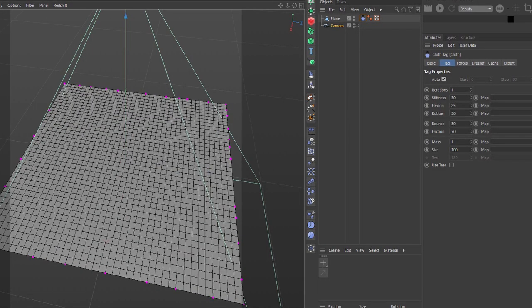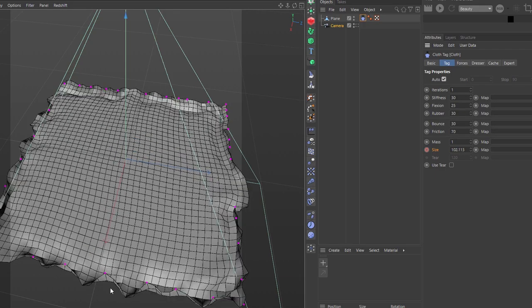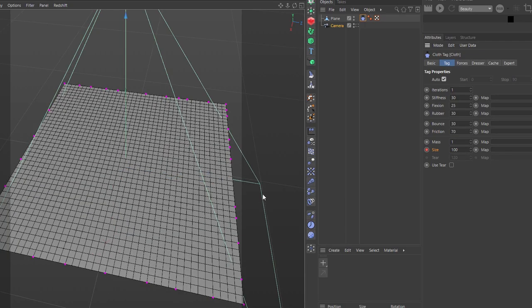And one more trick, we're going to size and hit this middle button to add a keyframe, frame number 10, 100, and in between we can add some external size growth. What it does is push our cloth to the side to 130% and then shrink it down.